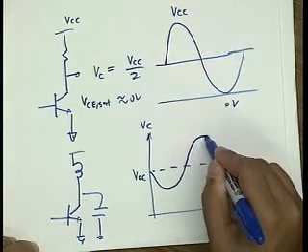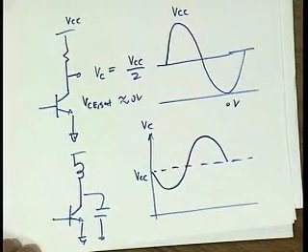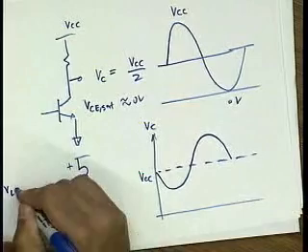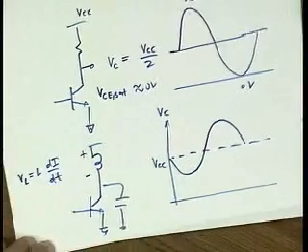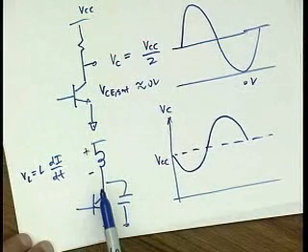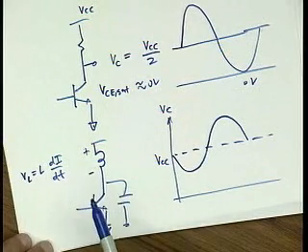On the other hand, you might be able to see that this voltage could actually go above VCC. That's because the voltage across an inductor is proportional to the rate of change of current. So if I'm increasing the current in this inductor, the voltage is positive. If I'm decreasing the current in this inductor, the voltage can go negative.